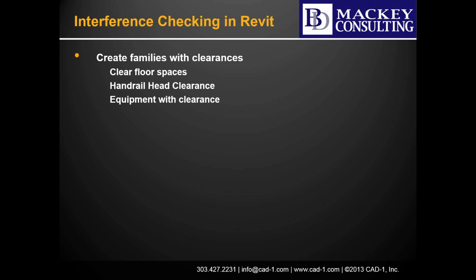Or if you start modeling equipment, so maybe you're an MEP firm, and I know this is coming into play with a lot of MEP firms. I've got to have access to this object in the ceiling, so they're going to go ahead and model a clearance down to the ground where they're going to need the clear floor space. Or in front of a panel, we model the clear floor space in. And it's a little bit different than just drawing rectangular lines in plan that represent that. We're going to model something 3D so we can truly use the interference checking.